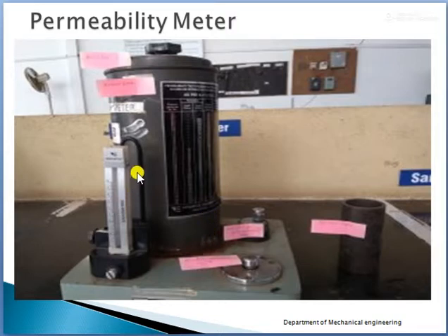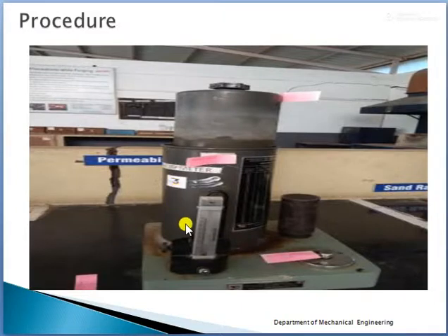Then next the manometer reading is set to 0. How is this set to 0? Here we have a setup with 0, 1000 cc, 2000 cc; you have to bring the mark 0 to this point. Then the manometer is set to 0. Then the air tank is kept inside the water tank. This is a bell jar or air tank which is kept inside the water tank.